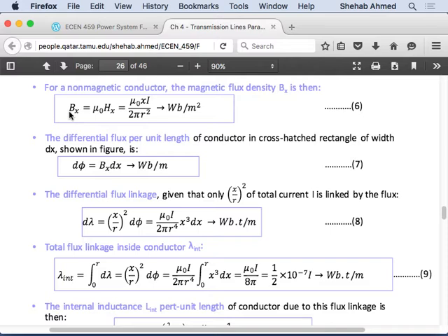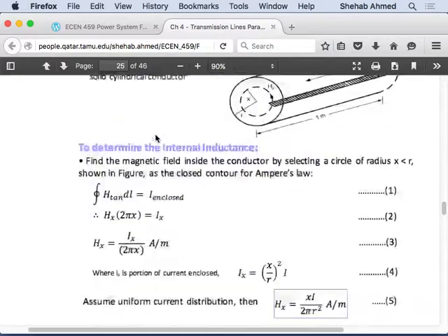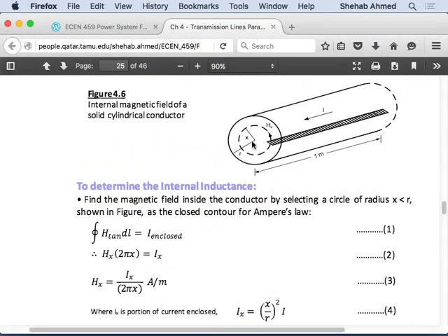Integrate over the areas. So integrate the flux density over the full area. The area was this dx section and 1 meter in length, so this is dx by 1 meter. It just happens to be, because dx is this extension of x here. If I increase this circle radius a little bit, it's dx, right? This is where the flux lines are cutting perpendicular to this area. This has a width dx and length 1 meter.